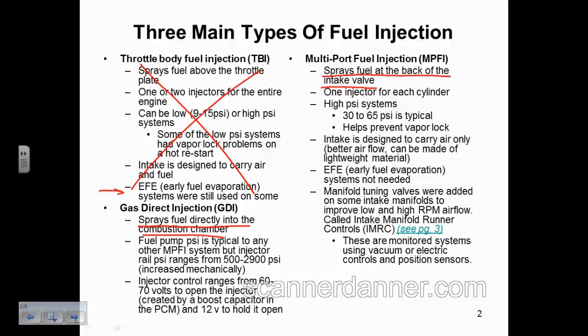That highly atomized spray topic really isn't reality on some of these injectors. Some of them had a stream type spray, and the way they handled that was you spray the fuel at the intake valve, which is very hot, and it immediately vaporizes. You don't even have to have good injector performance, just count on the temperature.